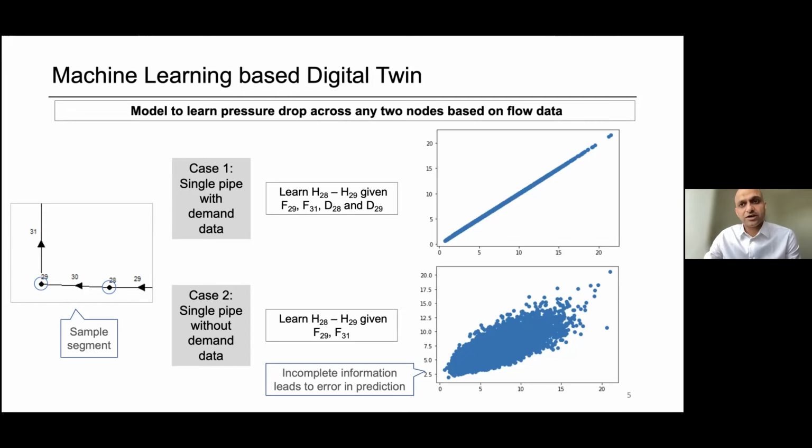Here in the approach that we're going to discuss, instead of, say, finding out or calculating pressure at a point or flow at a point, for reasons which will become obvious with the presentation, we chose to predict pressure drop between any two points where the measurements are being taken, given the flow in the vicinity. So there are certain assumptions where we assume that there are places where, in the close vicinity, or best case at the same point, we are measuring the flow and pressure.